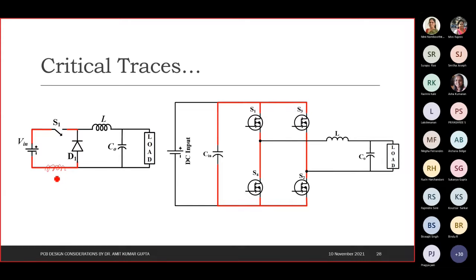If this line, as well as this line and also this line, has a parasitic inductance, and we suddenly switch off, then the current which was flowing through these inductors, we cannot interrupt it. What will happen to that? That energy or that current will oppose the sudden interruption, and that energy will combinedly appear across the switch when the switch is getting turned off.